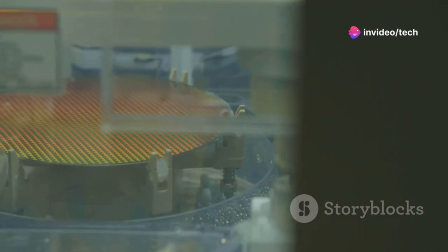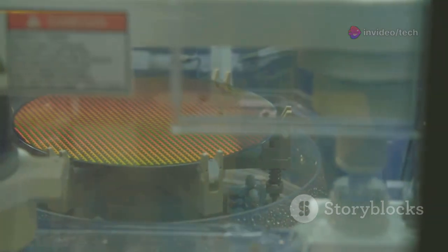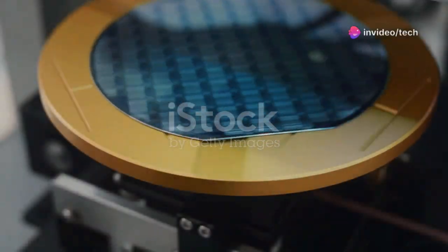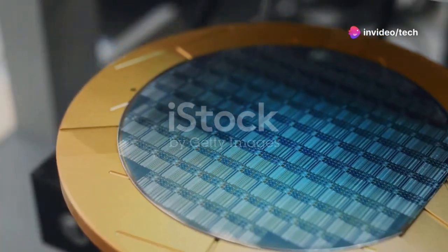The next step involves growing large, cylindrical crystals of this purified silicon, which will eventually be sliced into thin wafers. These wafers serve as the foundation upon which integrated circuits, the heart of microchips, are built. While pure silicon is a semiconductor, its conductivity is limited. To enhance its electrical properties, a process called doping is employed.